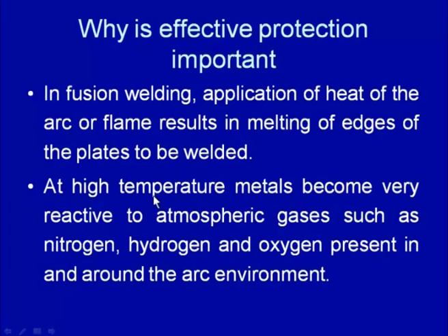These gases can react very rapidly with metals like aluminum, titanium, magnesium, and even in stainless steel the chromium can react very rapidly to form oxides and nitrides, which will either not dissolve rapidly or will remain present in the weld pool as inclusions, because of a density similar to the base metal or the weld metal.